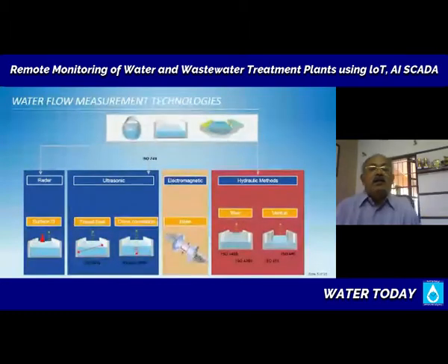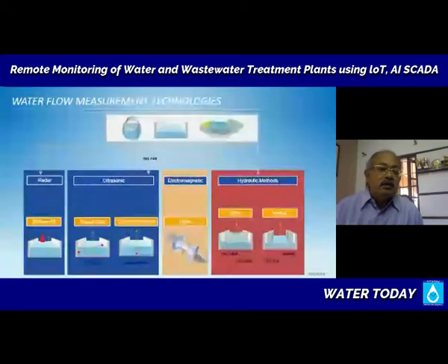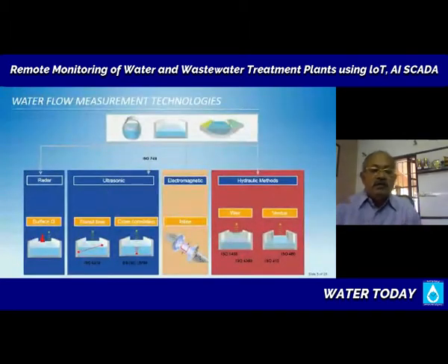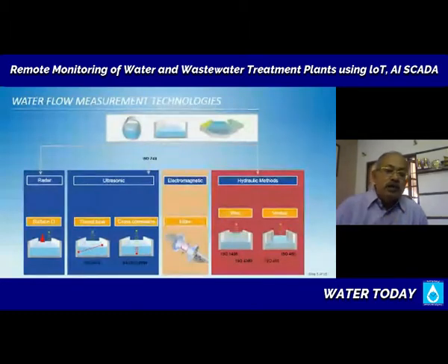Material travels in a magnetizing field as per Faraday's law that some of you may be remembering. It induces a potential, an EMF, electromotive force, within the water, and that is measured by electrodes. So you will have an electrode there which is measuring how much EMF is generated when the water moves in the pipeline. Obviously, as the velocity increases, the EMF generated will be more, and it is able to calculate the volume flow.